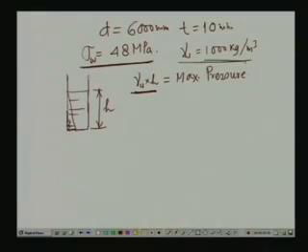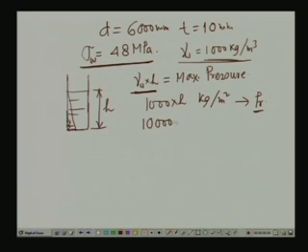Now, for gamma given as 1000 kg per meter cube, 1000 times H is so much of kg per meter square, which is the pressure being exerted by the water on the tank. If we write in terms of Newton, approximately taking 10, this is 10,000 H Newton per meter square. So, this is equal to the pressure P in this particular example.